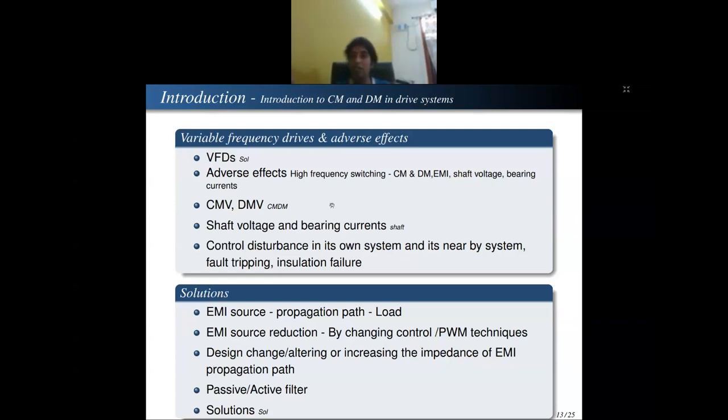In your inverters or any system, first there will be sensing. Many places there will be protection required, or based on some sensing you will take action. Say if my voltage reached, in a larger power level, 600 volt and above, you don't want to run the system. Then you will sense it in the sensor, stepping that value down to 10 volt. If this 10 volt is reached, it means in my main power circuit 600 volt is reached. Then what would I do? If it goes above 10 volt, I have to cut down. So this sensor has to sense this information.